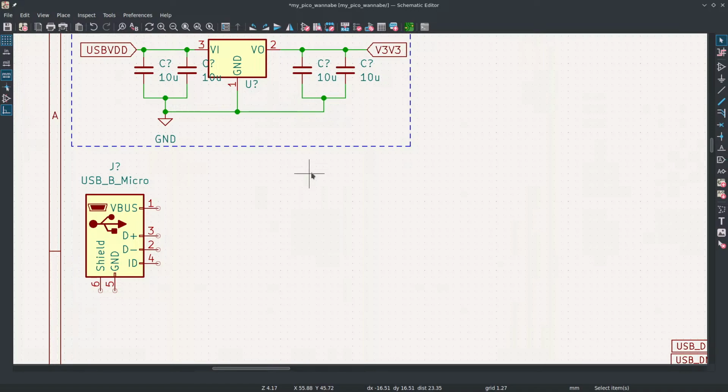Yeah, no, I did it under a microscope and still had to go in under the microscope, use an X-Acto knife to remove solder bridges. You have to have the perfect amount of solder because the pitch is so small, there are so many pins on a USB-C and it's so small. Is that on a hot plate or an air gun? So it was with hot air. And yeah. Let the manufacturer do that.